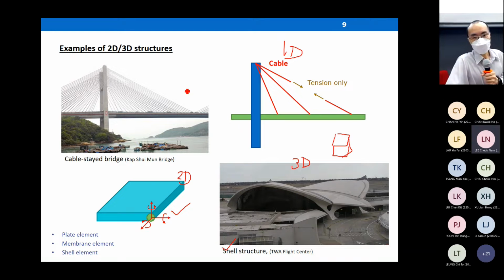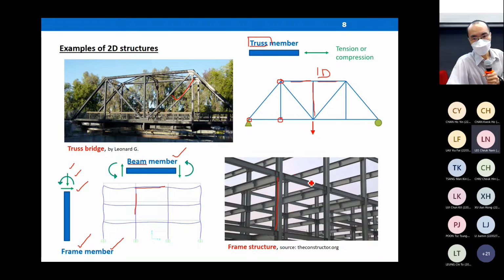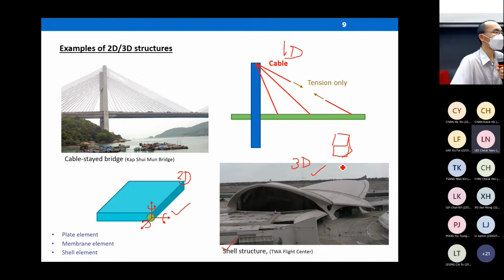Okay. A beam, right? We talk about beam. The model is a straight line in this picture. But actually for a beam, maybe I use a concrete beam, which is much easier to visualize. Instead of modeling a concrete beam using a straight line, actually you can cut a concrete beam into many small cubes, and then you join these small cubes together. It becomes a whole beam. This modeling is using 3D elements, many 3D elements.